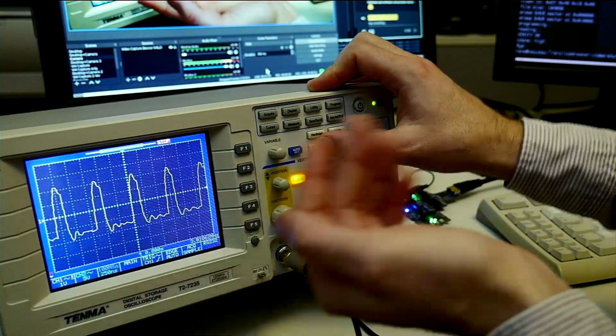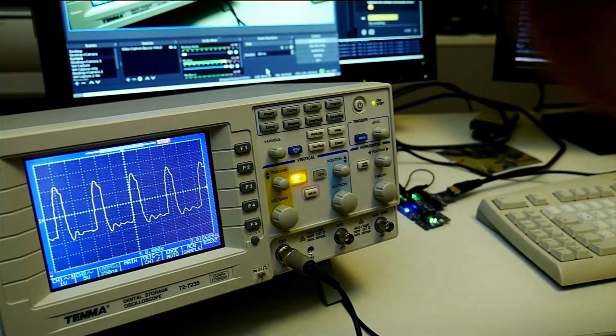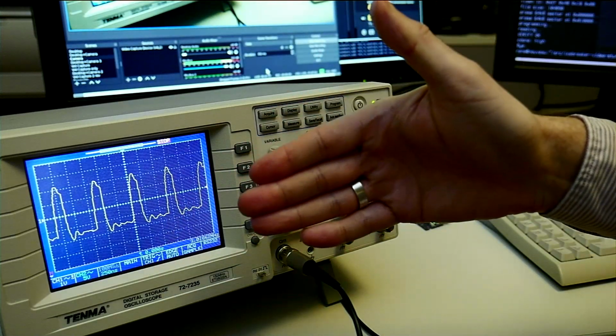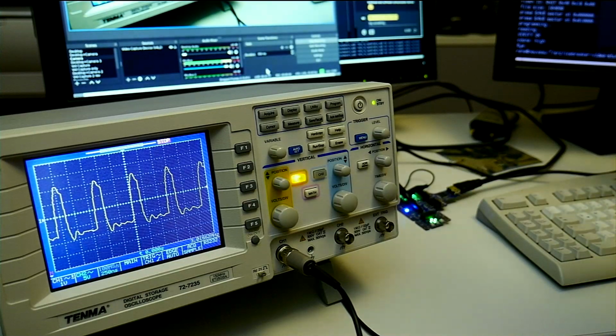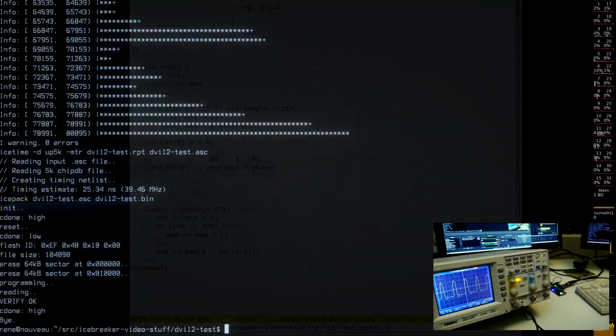But now you see it's counting very fast between no bit set to all the bits set. Of course, we also need to have some assignment there to generate the correct waveform. Right now we only count the bits through. Later we need to have a mapping of pulse width modulation of this value to how many bits are set in this. But just to illustrate this here.